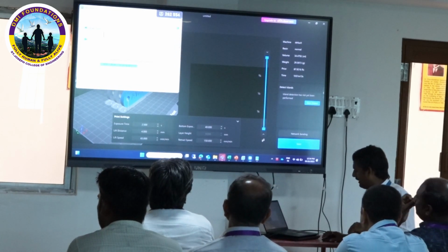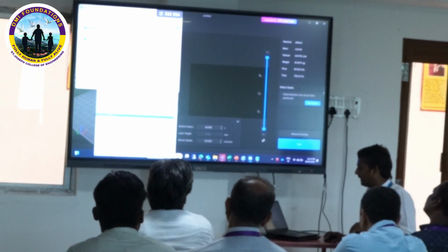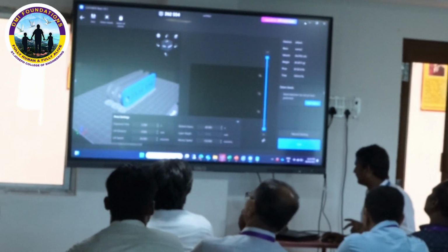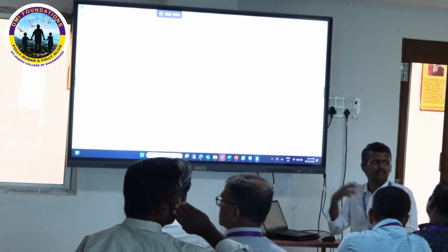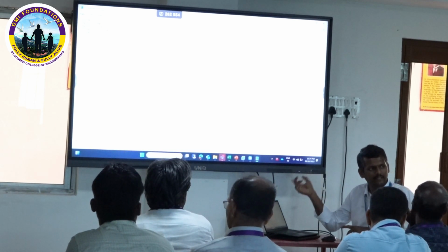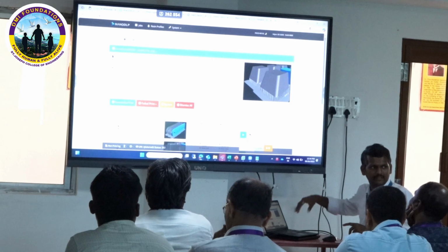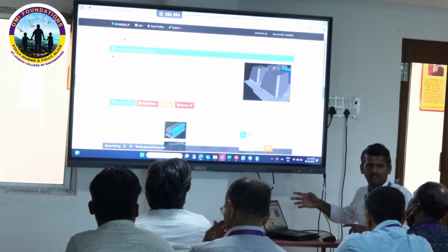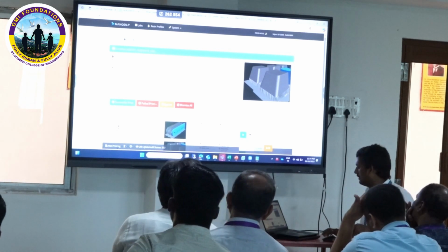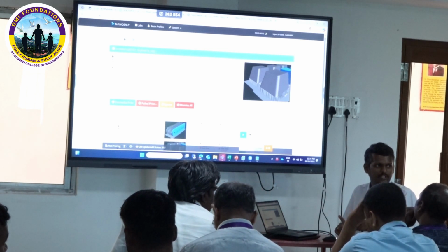Here we have different options, not only CWS, there is also a file format for the box. All these file formats are there, but we use the slicer output, not STL. We do have the option of uploading the STL, and the slicing can happen inside the IoT platform itself. But we have more options in the slicing software than in this one. The final file will be a zip file, a combination of both the G code and the images.